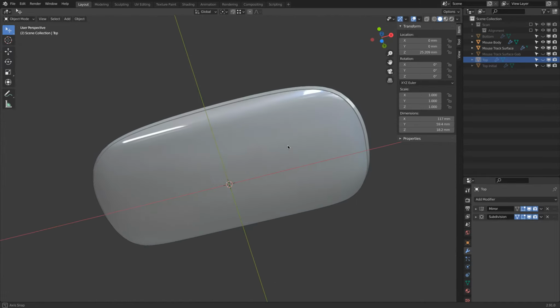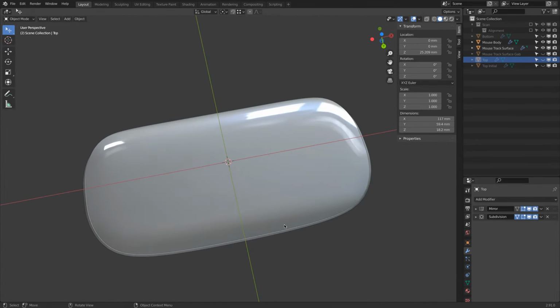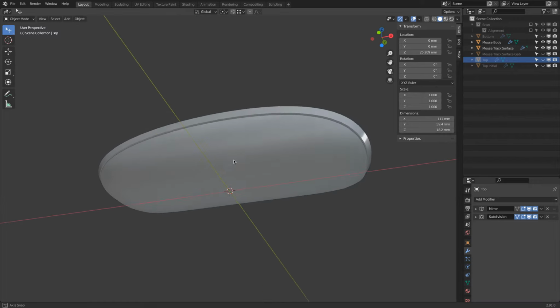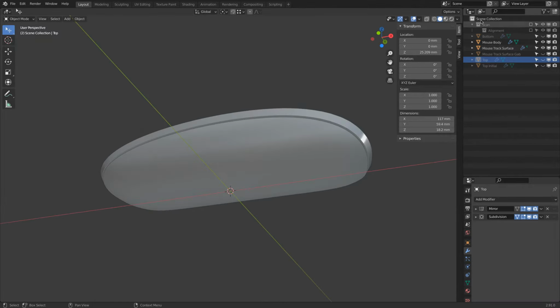Now it's time that we can create the interface at the bottom. But before we do this, we want to maybe clean up our collection here a little bit, because this is getting a little bit out of hand. First, let's make one new collection, and we can call this Rebuild. Into this collection, we just put the two final objects in. Then make a new collection, and we can call this Trim. And then here, those objects we drag in there.